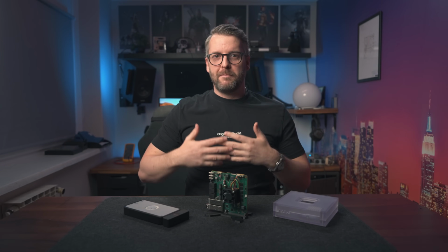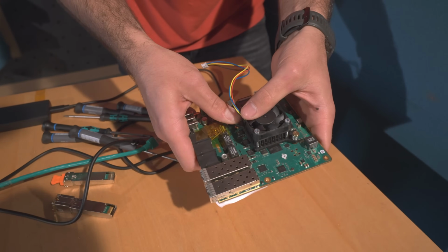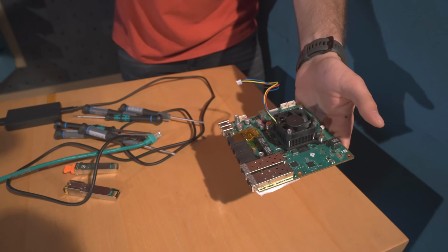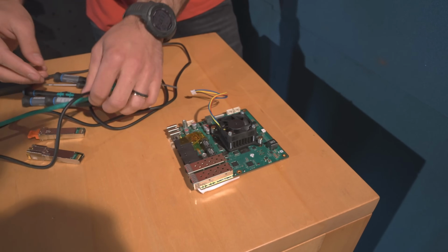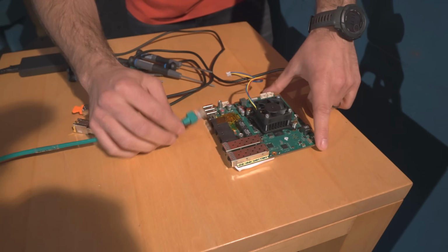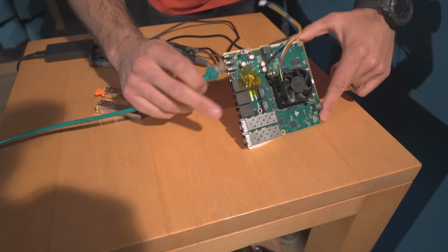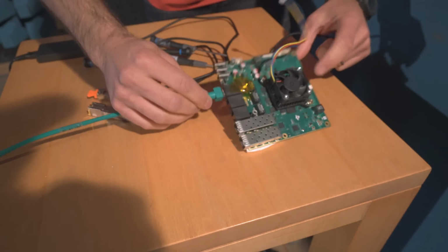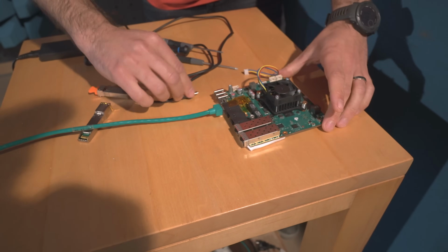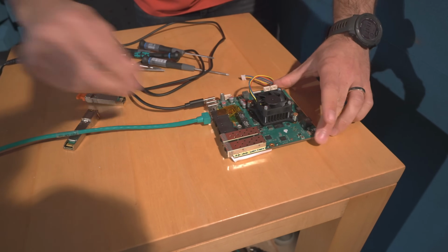We tried a number of possible orientations. We tested it with aluminum enclosure, with polycarbonate development kit enclosure, and even with the bare naked PCB. And each of those tests, to my immeasurable happiness, turned out positive. As in, we comply with what the European standards for electronic devices dictate for a class of device like ours.